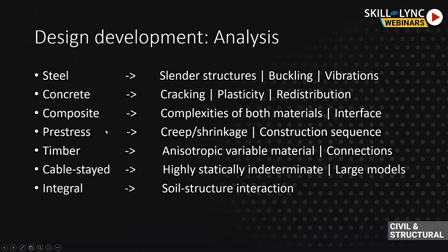Pre-stress is advanced, and you're talking about a lot of long-term behavior like concrete creep and shrinkage. You also need to think quite carefully about the construction sequence and stressing sequence for your tendons. And timber is quite complex in the sense that it's a very non-uniform material. It's anisotropic, and it's often driven by the connection rather than the timber body itself. Cable stays are advanced. They're really like a geeky side of engineering. They're very statically indeterminate and difficult to design.